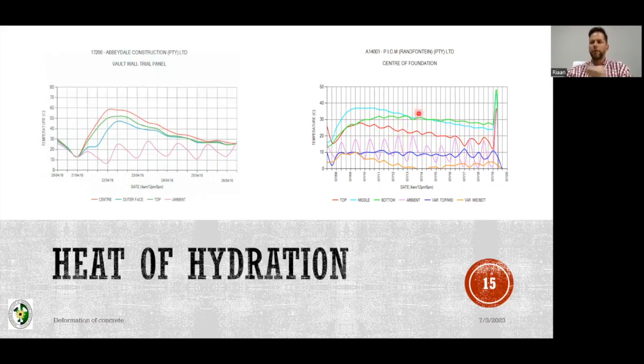And if you don't plan for this, your contractor will complain, because he says, I cast the concrete today, 2 days later I strip all the shutters, because those shutters will have to be moved over to the next pour, to the next cast. And if I'm not doing that, I'm losing production. So we were able to establish this beforehand, and the contractor was able to then price accordingly and stagger his costs. He could bring a smaller team onto site.